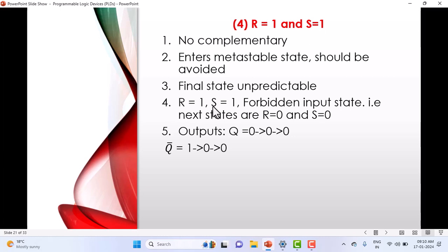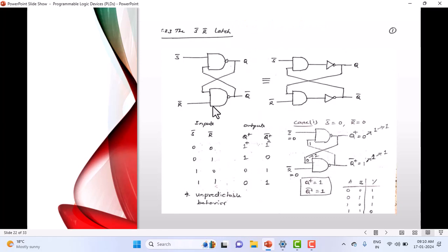That's called the metastable state. Alright, now let us come to another latch called the SR latch. You should not call this SR latch, simply it is the S bar R bar latch. What is the difference between the previous latch we have discussed, NOR based, and the present one? We changed the gate, right? Instead of having a NOR gate, we preferred NAND based here. And there is a reason why we have gone for this S bar R bar latch. The reason is I want to build an SR flip flop. For the SR flip flop, which is NAND based, this serves as a part of that.